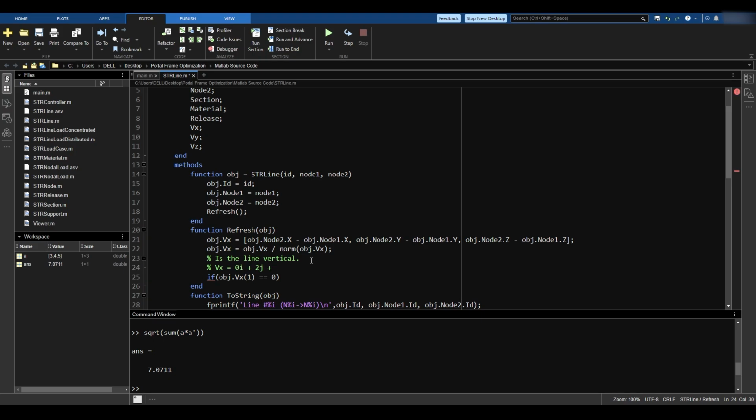This is not a vertical vector because it has components in the x or y. But if you have 0, 0 in x and y, then this is a vertical vector. Of course, it would need to be normalized, so it makes 1 here, but it still stands. You would have nothing in x, nothing in y, and everything in z, positively or negatively. This needs to be checked. But the problem is, once again, due to numerical accuracy, you might have 0.001, and this will freak out the calculation. And this will cause a lot of problems.